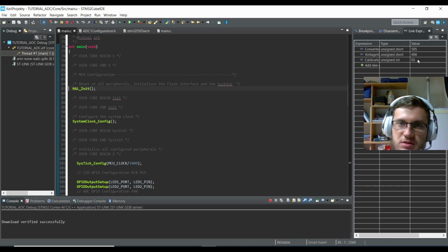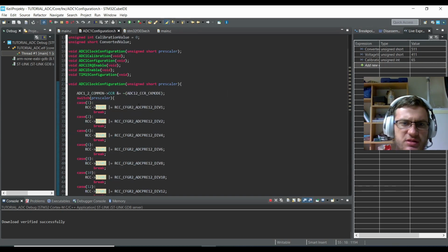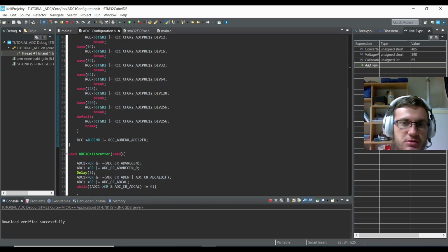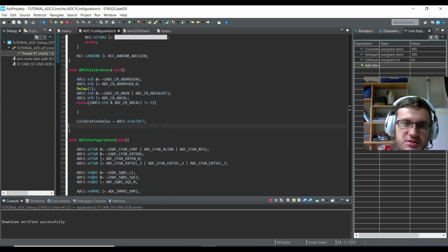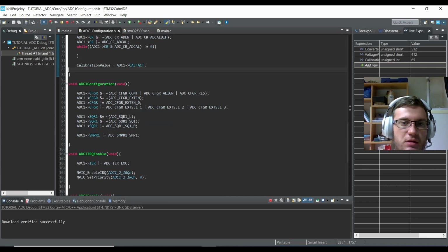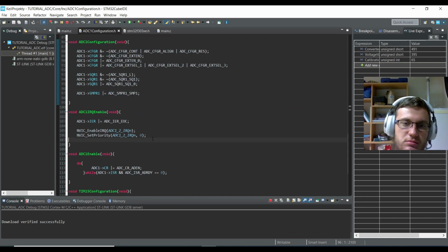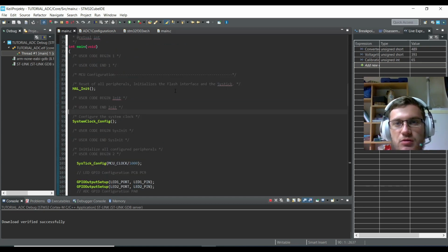And again, if you want a faster refresh rate, inside the header file you will just rewrite the configuration of the timer. If you want a different resolution, you will switch the resolution inside the configuration of the ADC. What else would you want to do? Maybe change a calibration factor, but there is not much to do. Of course, you can change your prescaler. Over here in calibration, basically there is nothing to change. This is always the same. Yes, and if you want a different sample rate, right now I have the slowest sample rate in interrupts.